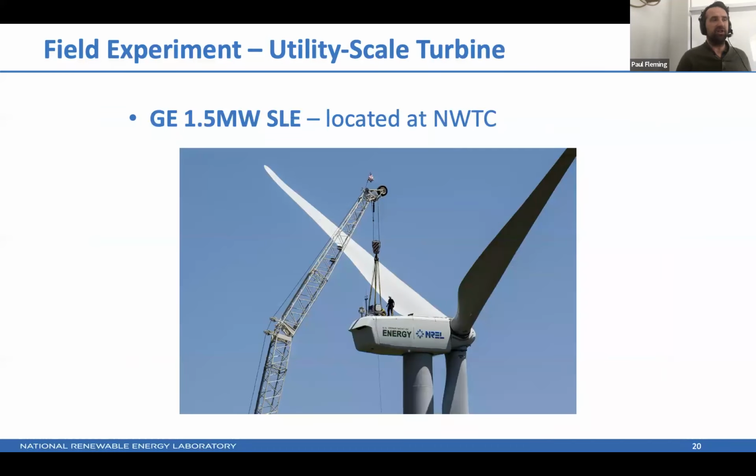Another opportunity from this test was that this turbine is highly instrumented with load sensing. So it gave us an opportunity to assess the impact of doing this yaw misalignment on the loads from the turbine. We could look at the impact on blade root bending and tower bending, and different vibrations experienced along the shaft. And there's a pretty thick paper on those results and an even thicker internal report. But I would say the key takeaway is you can design a region of operation of a reasonable amount of offsets happening in reasonable wind speeds where the impact on the loads is not too much.